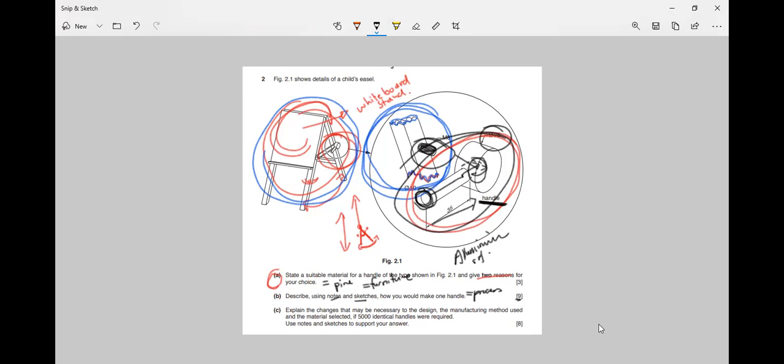Do you think something like that would be necessary? I think wood glue, because I cannot insert a screw because it will interfere with the rotation of the, what you call it, the rod, the threaded rod. Exactly. And remember that that threaded rod also needs to be inserted into that peg, but from a different side. So you're going to have to estimate the distance between that space and that space so that the threaded rod does not bang up against that peg. Okay, so all of that you need to discuss in this process.